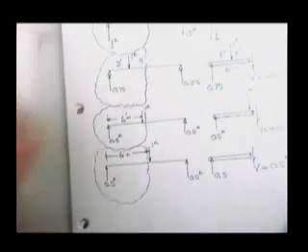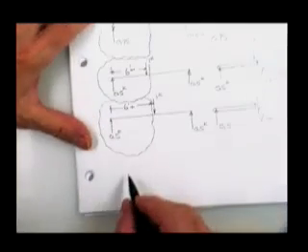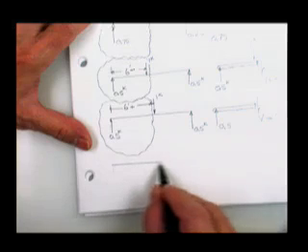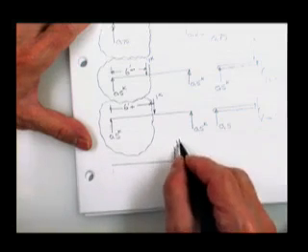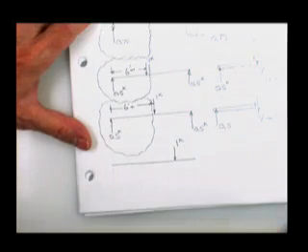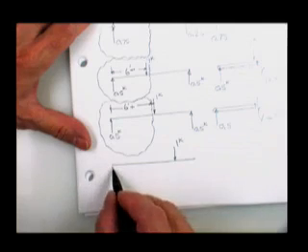We okay? All right. Finally, I'm going to draw the beam. I'm going to show the 1 kip load. I only told you I was going to do a couple of points because they were always straight lines. And it turns out they really are. The shear influence line's got a kink in it, but it's still made up of a pair of straight lines.